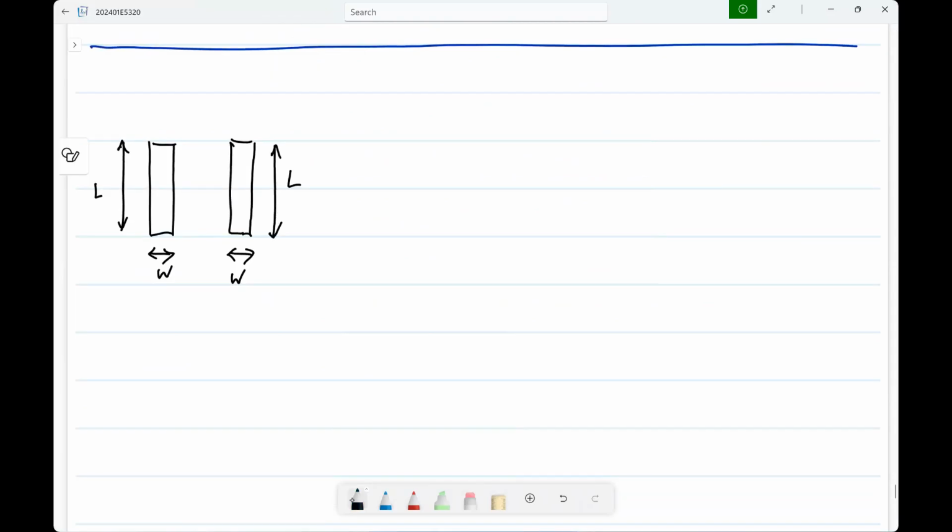Now, at this point, you have come down to something that you can't control at all. For instance, the resistance of any material is related to the number of free carriers available there, which is related to doping. The number of dopants per unit volume is not exactly identical, because of this discretization, there will be some statistical variation in that. And this width and length, I am drawing these as absolute straight lines, but there also there will be some jaggedness.